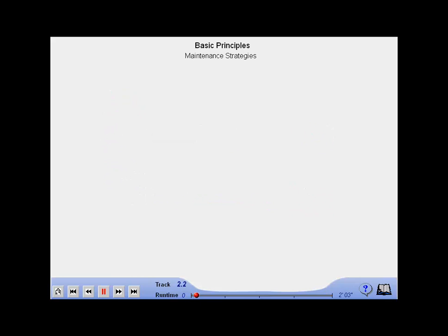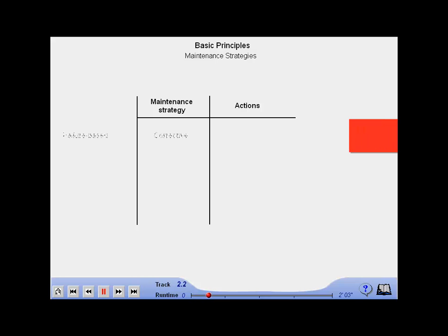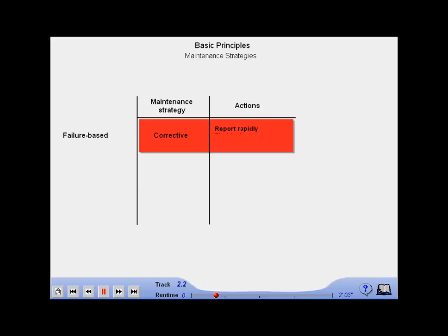Technical diagnostics is integrated in an overall maintenance strategy whose primary task is to ensure high availability, especially in production systems. In the corrective case, in other words when a unit fails, the system must rapidly display the fault, locate its cause as precisely as possible, and support the operator in clearing the fault. The savings potential is highest here because standstill times in the production process can be reduced.